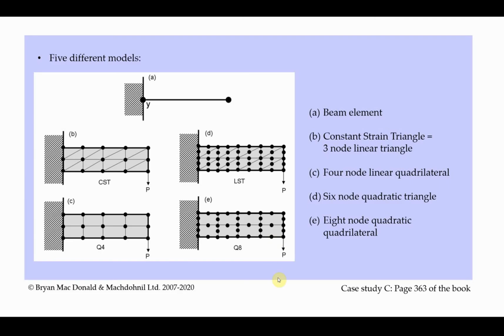So this tutorial was really just a way to show you how to get more control over your 2D meshes using ANSYS Workbench, how you can change between linear and quadratic elements, how you can force a model to be meshed according to the divisions that you set, and just again changing that hard and soft option, and how important that is, and also how you can check the number of nodes that you have in each element and that you are in fact getting a linear or a quadratic element.